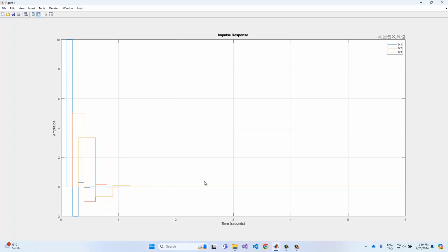Okay, this is most important, because if we have this signal, then we can convolve the whole signal based on our system, the Z transformation system. This generates our template pattern for the Z domain transfer function of our systems. If we have this condition, then we can convert everything in the time domain, especially for the discrete time, and then we can generate the different responses for a given different sampling period in our signal.